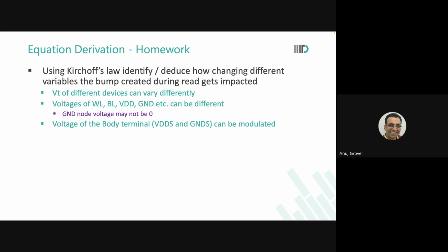We want Vx to be very low, all of us. So let us assume that Vx is actually low. If Vx is low, then this device is going to be in saturation. If Vx is low, then the pull down is going to be in linear region. Just the equation has to be different, but the current has still to be the same.